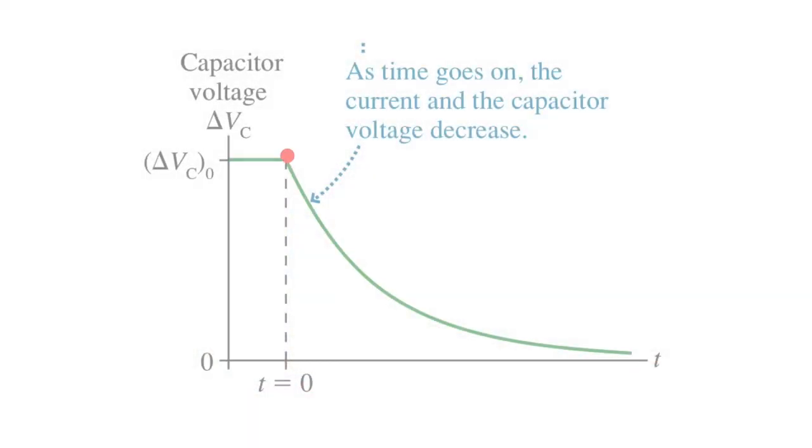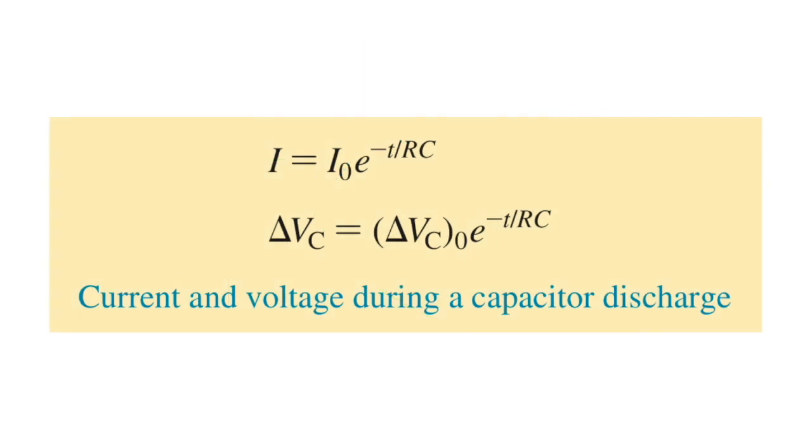We have a diagram in the book that shows the voltage decrease in a circuit like this. And what you see is this. As time goes on, the rate of decrease of the voltage decreases. So it's an exponential decay that sort of slides its way into 0. And it's an exponential decay, as we saw previously when we looked at damped oscillations. But it's an exponential decay of the voltage.